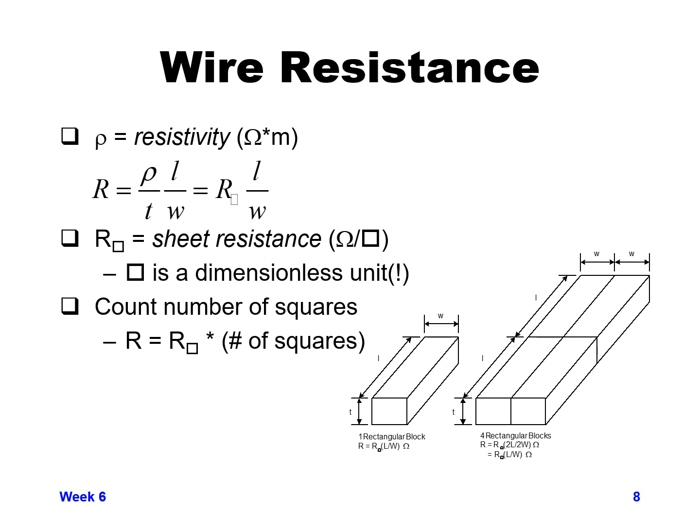So the resistivity of your metal divided by the thickness of the metal for a given metal layer is a new term that we're calling the sheet resistance for that particular metal layer. So all of your metal 3 wires, for example, will have the same sheet resistance, which is given in ohms per square. And square is basically a dimensionless unit.